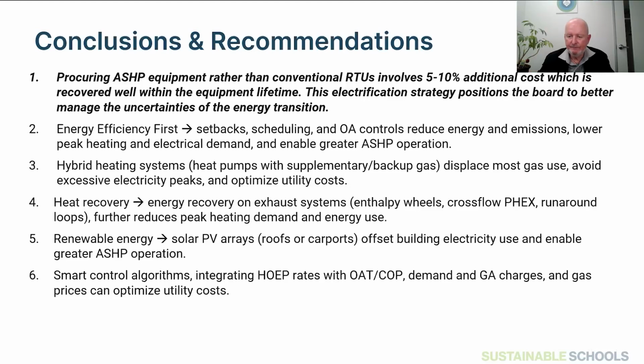So what we found is that the premium to go to a hybrid approach rather than a standard straight rooftop replacement, as you mentioned, is 5 to 10%. So it's not a big premium to pay. At Chesterly, those units were actually sized for the previous cooling capacity of that unit. So the retrofit was very straightforward. There were no additional electrical requirements. We had all of the existing hot water lines in place. So it really didn't complicate that project much at all. So we think it made sense.